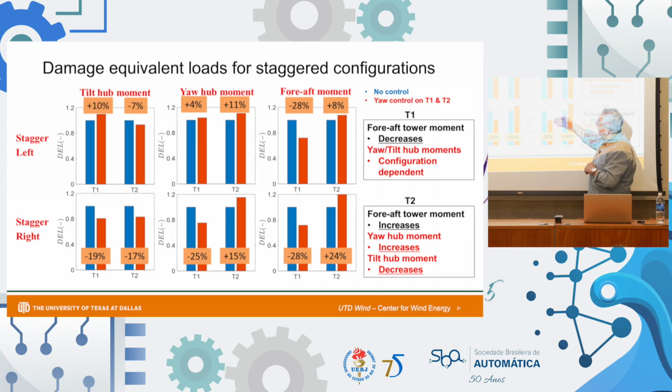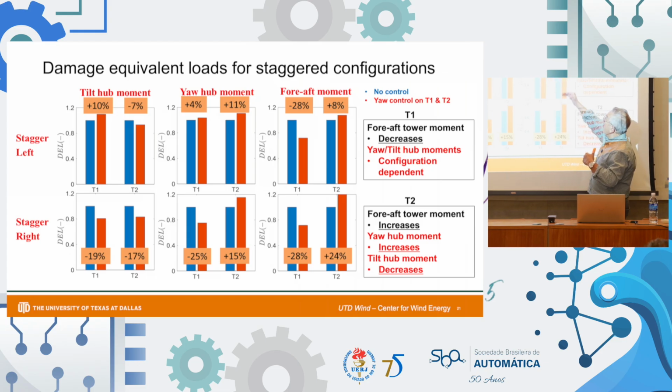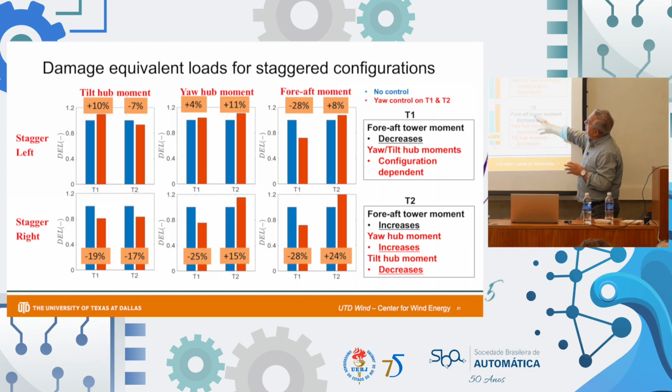As you can see, decrease in the first turbine because I see less wind. In fact, what you see is V times the cosine of the yaw misalignment, all of that cubed. That's what is pushing you. So it decreases there, but the second one sees more wind coming in, so they go up. The loads that I'm showing are called damage equivalent loads. That's a very technical concept that involves a lot of explanation, and I don't want to get into that for this audience, but just think about these as loads that reduce the lifetime of a turbine.